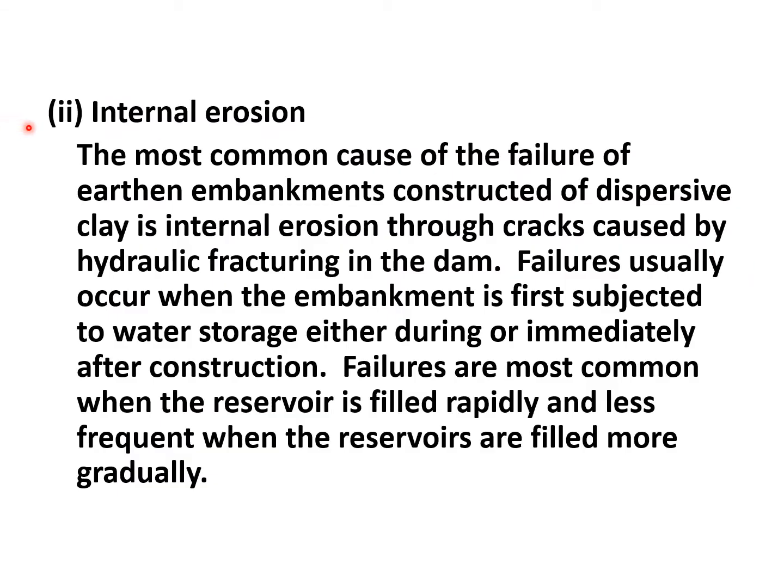Second is because of internal erosion. The most common cause of the failure of earthen embankments constructed of dispersive clay is internal erosion through cracks caused by hydraulic fracturing in the dam. Failures usually occur when the embankment is first subjected to water storage, either during or immediately after construction. Failures are most common when the reservoir is filled rapidly and less frequent when the reservoirs are filled more gradually.